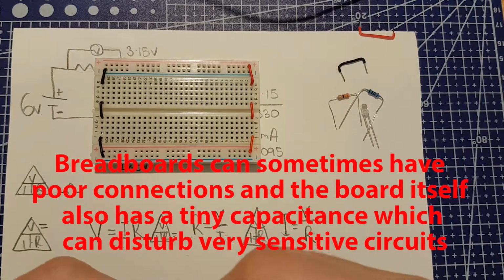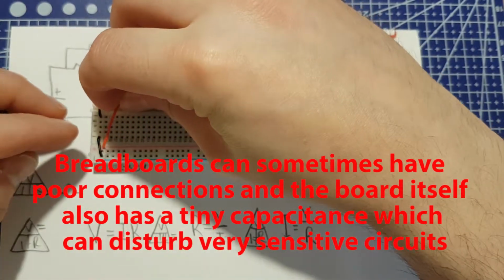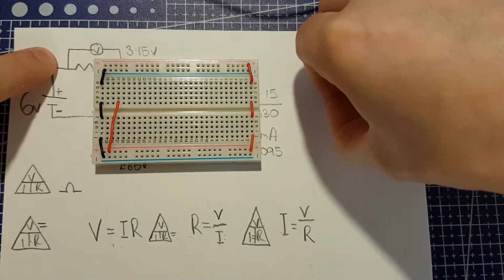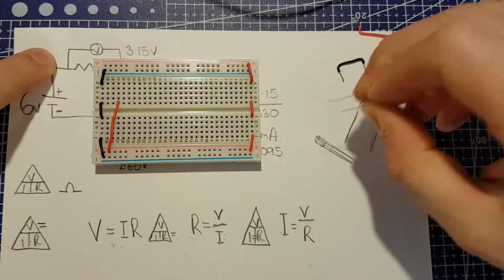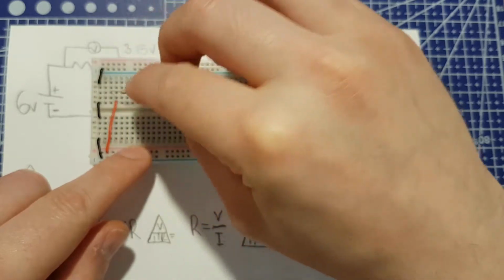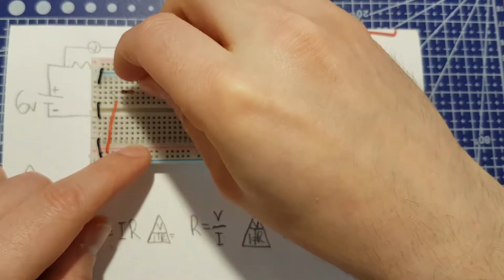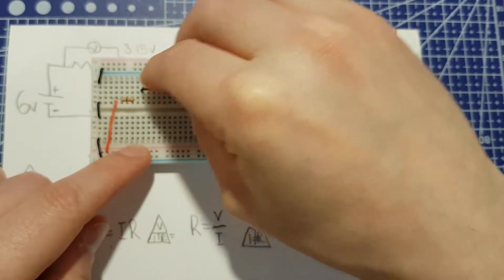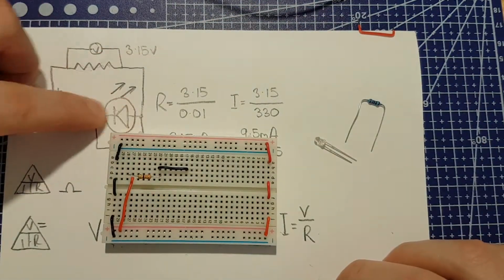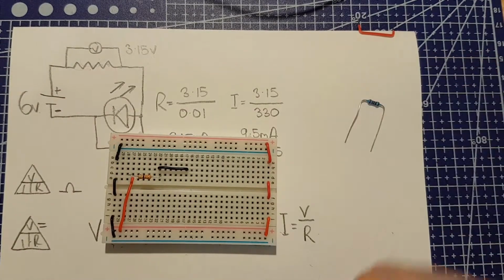So we've got a positive supply on the breadboard. I'm going to bring that up with a jumper cable, and then from the positive supply we're going to go into our resistor, which is our 330 ohm resistor, just there. From the resistor I'm going to put another small wire, which represents this wire here, just to space it out a little bit. You don't have to do that on the breadboard, but I'm going to space it so it makes it easier for us to see the meter.